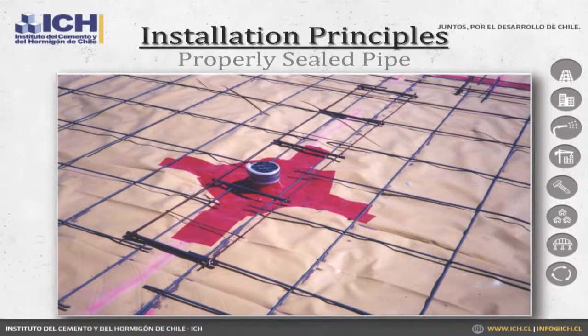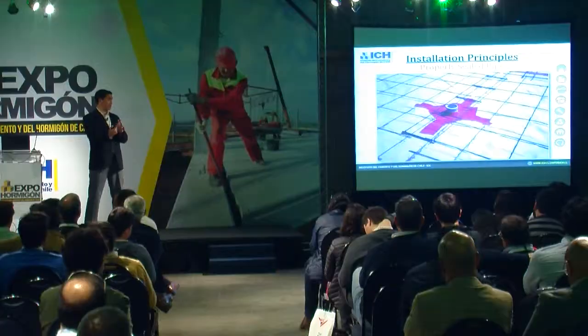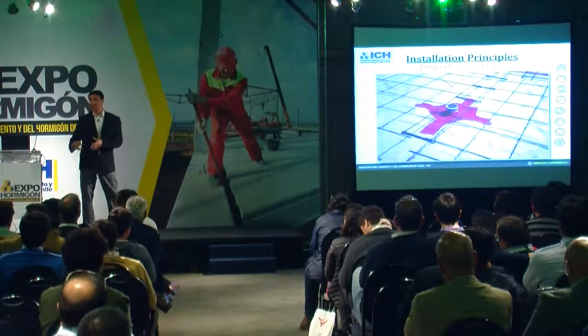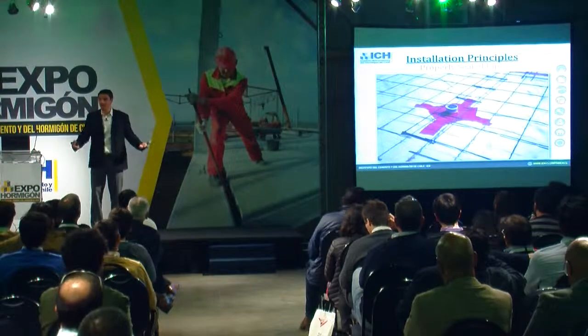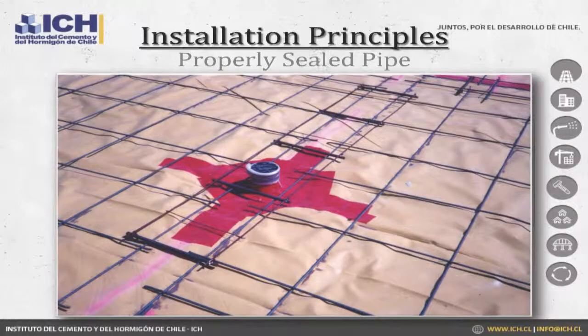Around pipe penetrations, you're supposed to seal. This is the standard, states that you seal all the pipe penetrations with tape. You're trying to create a bathtub beneath your building, basically.